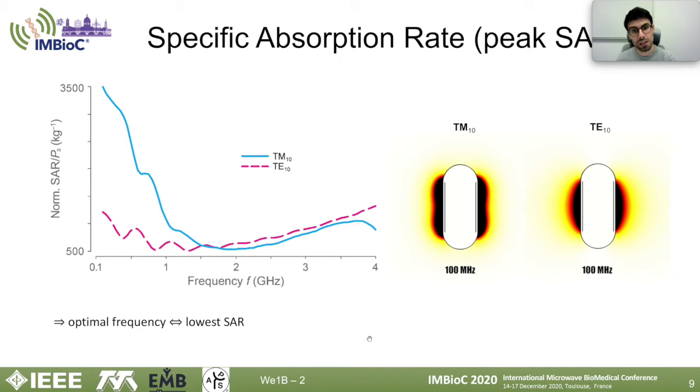The same model allows us to also predict SAR, how it will behave over frequency, and clearly the dissipation is the lowest at the optimal frequency range. Note also that at suboptimal frequency, the dissipation is significantly higher for electric sources, which means it is better to avoid this scenario. However, considering the very low input power of modern implants, SAR is generally not a problem here. However, it may be important to remember this for potentially more powerful wirelessly recharged devices in the future.